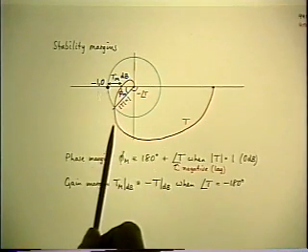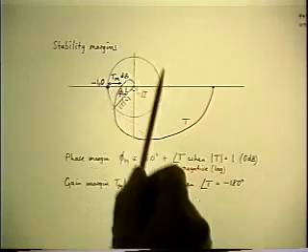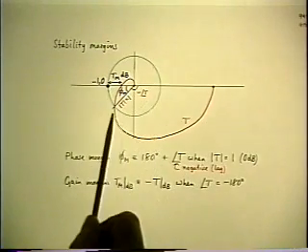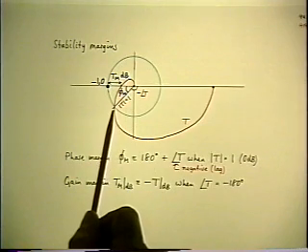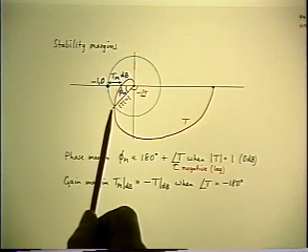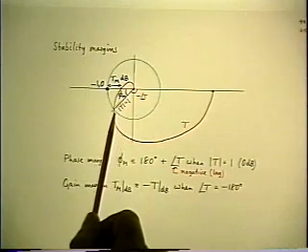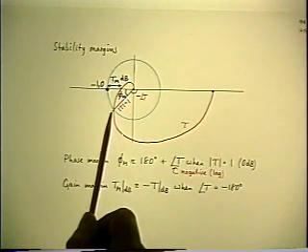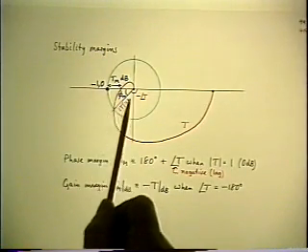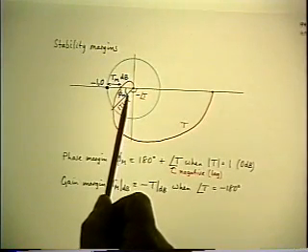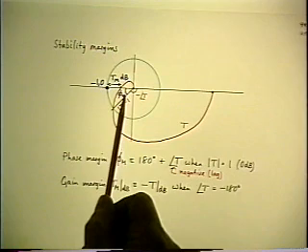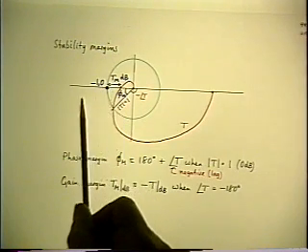So the first standard definition is, you draw a unit circle around the origin and you find the point where the contour crosses that unit circle. That frequency, of course, is the crossover frequency. It's where the magnitude of the loop gain is 1. Now, at that frequency, the phase lag will be less than 180 degrees. And how much less it is by definition the phase margin.